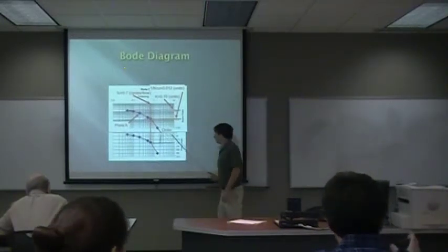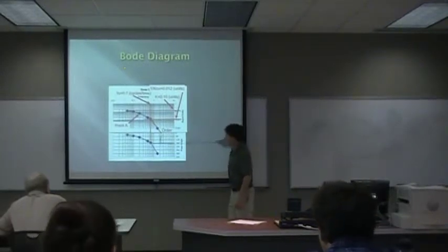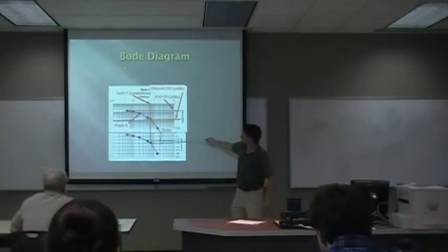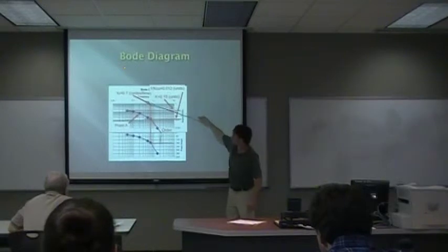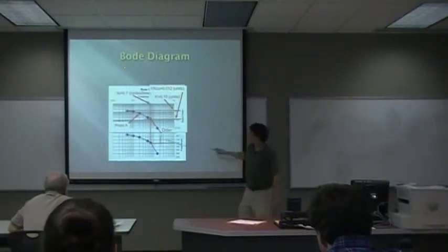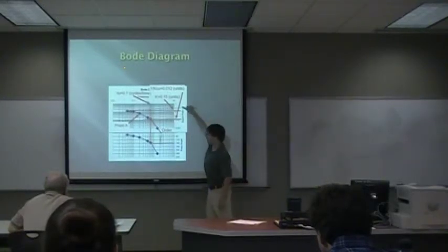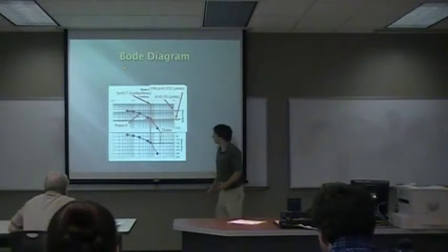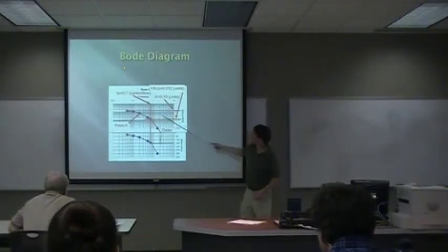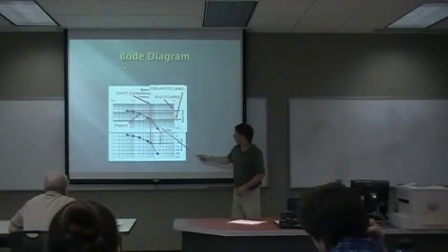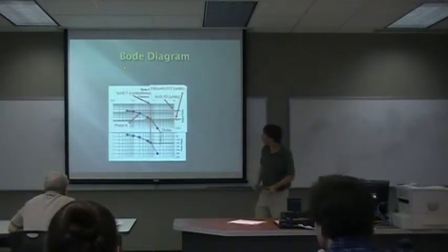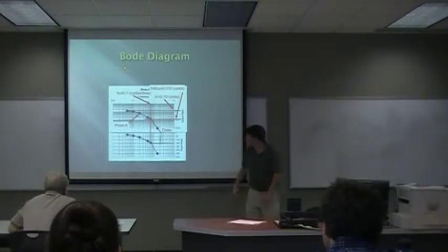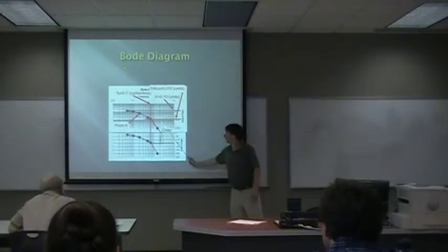And then as you can see from this, you go from 180 degrees to where it intersects your graph, go up, and this gives you the frequency for the system, where the system tends to level off and follow a more asymptotic response. That's where you can get your K. And where it intersects right here, you can find your ultimate gain Kcu, as well as the order for the system.